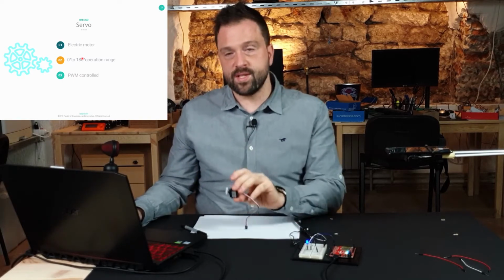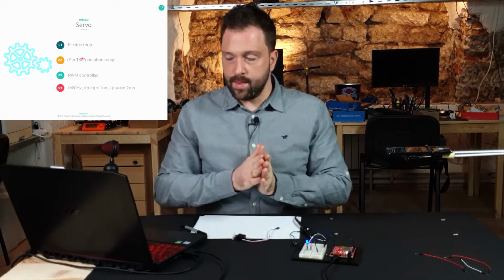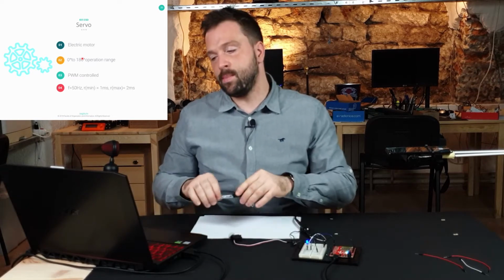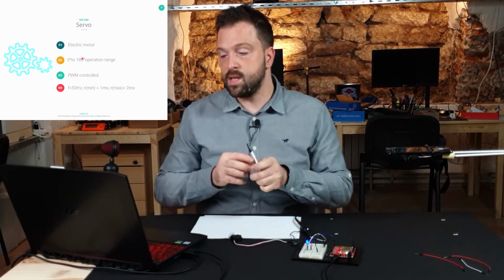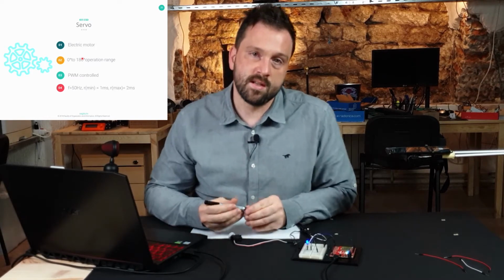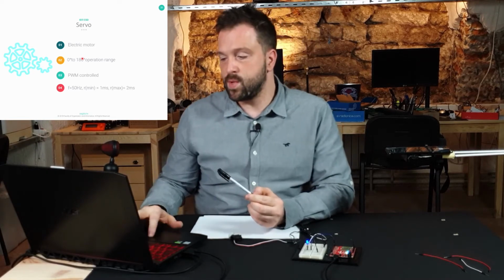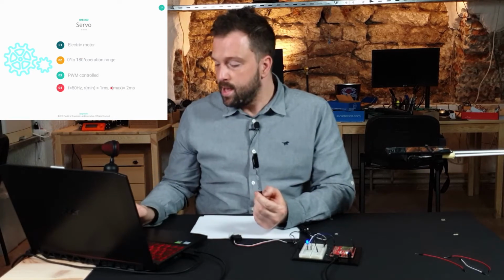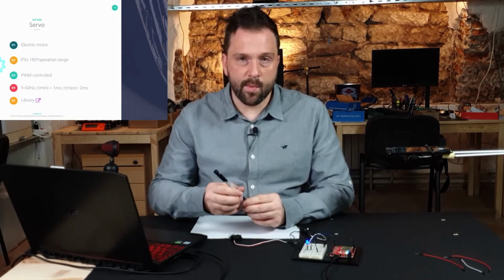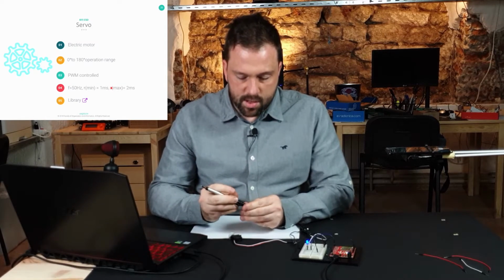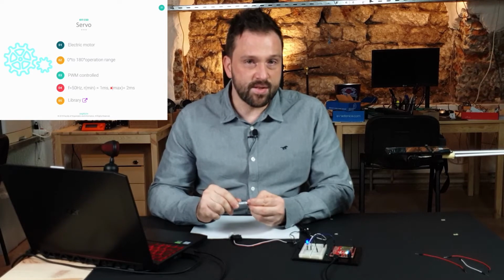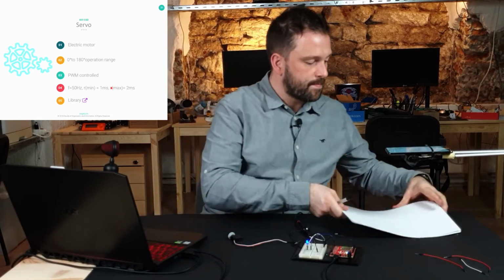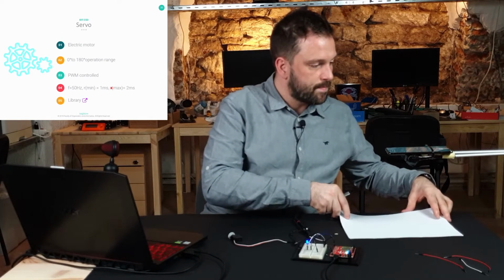So the manufacturer of this servo has defined pretty much all the necessary information for you to control the servo, like frequency, what is the width of a signal to the leftmost, and what is the width to the rightmost maximum position. And of course you can use the library in this case. However, we will do this manually. We will control the PWM signal. However, to get exact values, we need to do some math. It's simple math, don't worry.